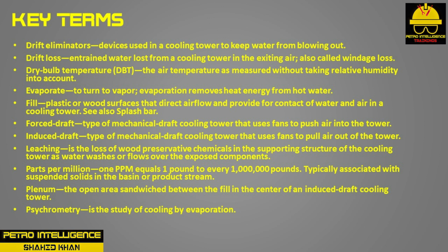Forced draft is a type of mechanical draft cooling tower that uses fans to push air into the tower. Induced draft is a type of mechanical draft cooling tower that uses fans to pull air out of the tower. Leaching is the loss of wood preservative chemicals in the supporting structure of the cooling tower as water washes or flows over the exposed components.